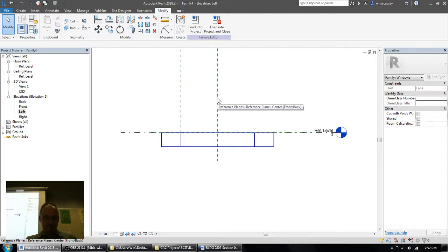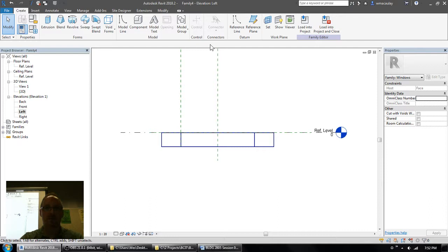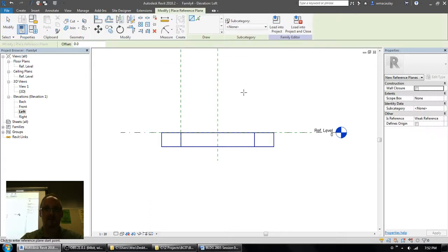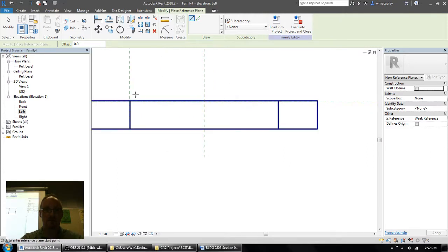Now, on page 5 on the center screenshot, you can see that we are adding 3 reference planes. So just watch me do it here, then you folks will be able to pull it off. So not reference lines, reference planes, and we're going to draw 3 of them. One just above the extrusion, another one just below it, and a third one just below that. So we're going to have 3 reference planes like so.